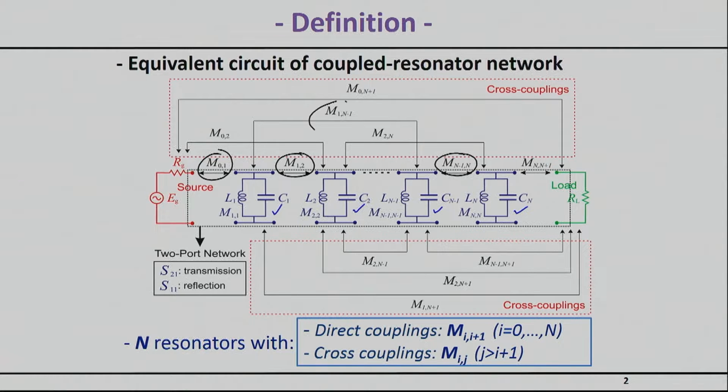So for example, this here is a cross-coupling section, and this here is a cross-coupling section. In theory, many filter responses need multiple of these cross-coupling sections. But it's also important to realize that even if you don't intend to have a coupling section, parasitics may introduce one.